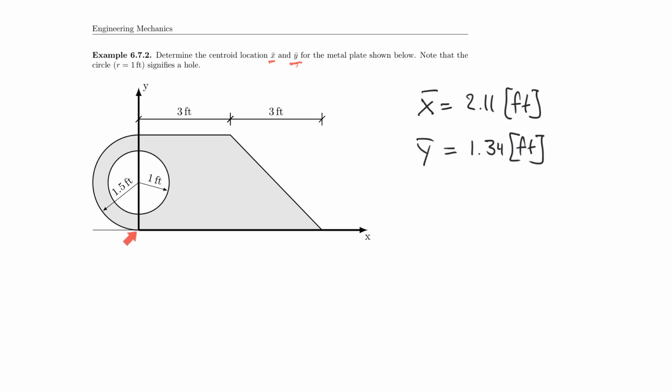here is a semicircle, and that semicircle lays on the left side of this coordinate axis of the y direction. So that means everything here on the left side has to be subtractive if you consider this your origin, similar to the problem that we solved before, right? And then also the circle has to be subtractive, but that one has a complete center. So it's a complete circle which has its center right on this axis, so your distance there will be 0. And I let you play with that.